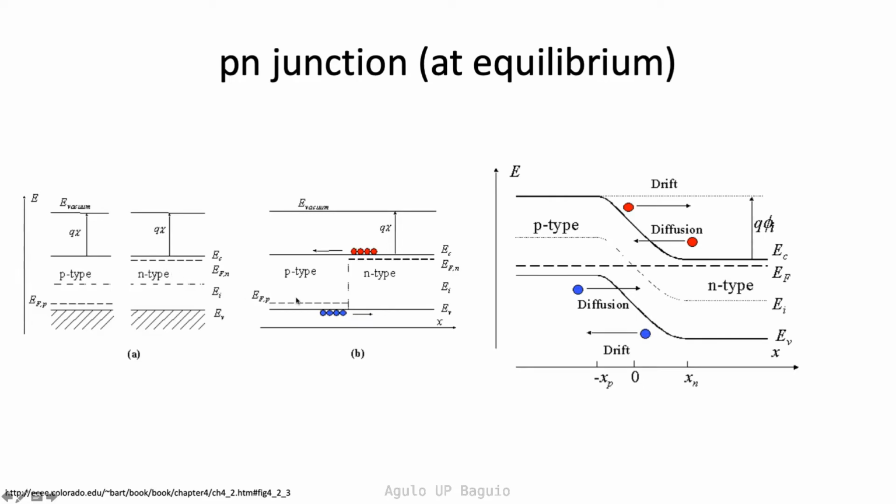Upon combination and before diffusion, you see the Fermi levels misaligned. The Fermi levels represent the highest energy level occupied by the charges of the atoms. Thus, these Fermi levels must align. You can therefore imagine that when the Fermi levels align, the p-type band moves up, while the n-type representation moves down. The final result is the figure to the right.